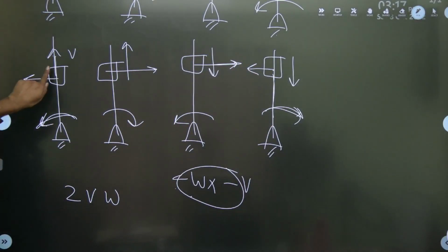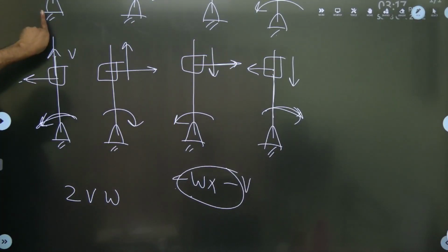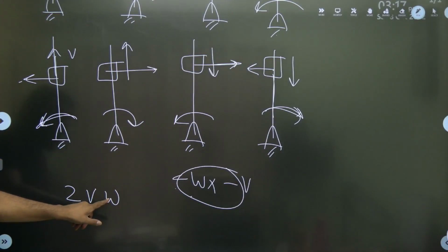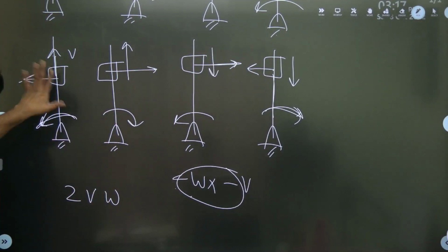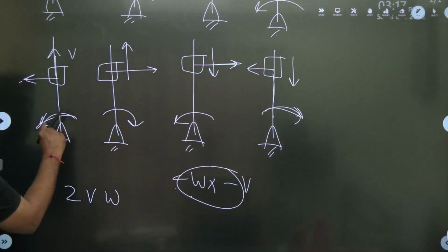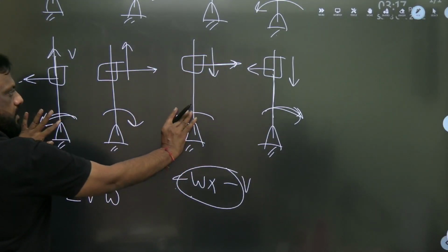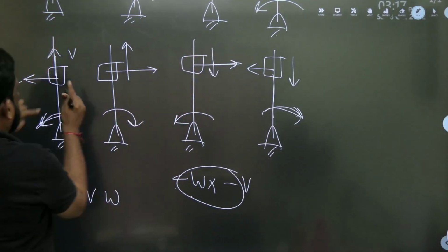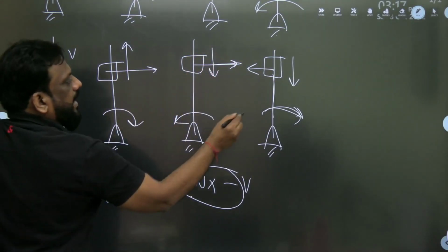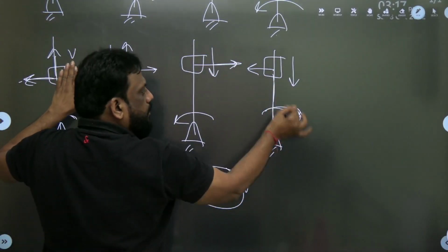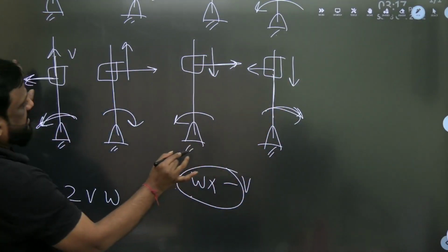Coriolis. So if you take upward plus, anti-clockwise plus, for example, anti-clockwise plus, clockwise minus. Therefore, with respect to this, you are getting opposite. Now this is downwards and anti-clockwise. Omega is not changing direction, but V is changing direction, minus. So with respect to this, it will be minus. And here V is negative, and with respect to this, omega is also negative. Negative into negative is positive. Positive means same as this.